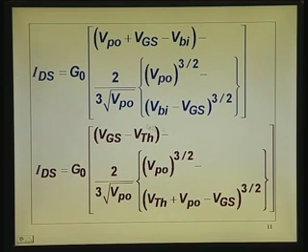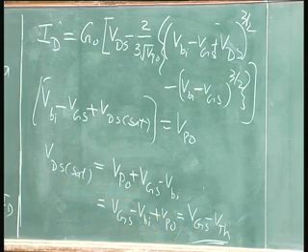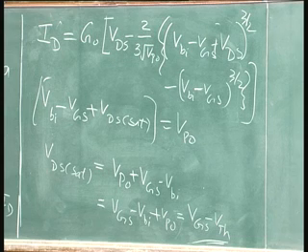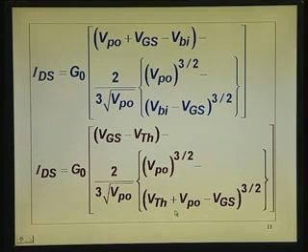I do not want to put it as Vbi, we want to put in terms of Vgs and V threshold. So, for Vbi here we write V threshold plus Vp0, since Vbi minus Vp0 is V threshold. That is all what we did. So, we have got now everything in terms of Vp0, Vgs and V threshold. Let us see how it changes.